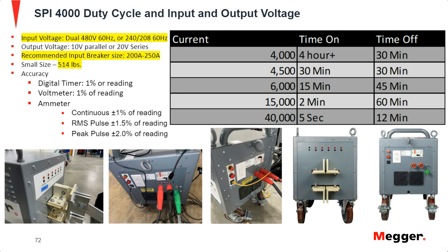Yeah, so it won't be harmful to the breaker. You're testing at under what it's rated for. All it's going to do, if you run it for super long, is you might see some smoke. That'll just be the dust burning off. For your 1200 amp trip setting, your long time setting could be 1.0, so 1.0 times 1200 will be 1200 for your pickup, and then you times it by 3. So yes, you're correct, 3600 amps. It's not going to be harmful to the breaker. These breakers are designed frame size wise to handle 100,000 amps instantaneous, 65,000 amps instantaneous. So it shouldn't be harmful if it's a 2000 amp breaker.